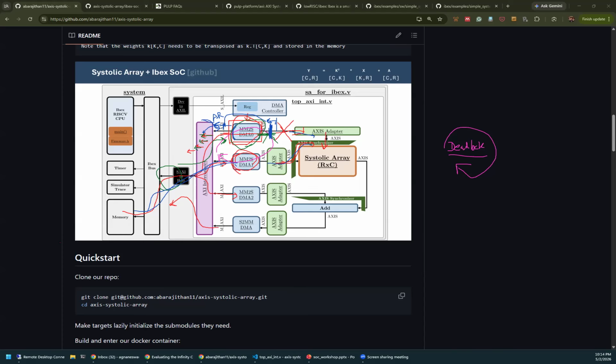All right, there is a question. When I went through the open source AXI repo, I found the AXI interconnect cannot have concurrent read-write transactions. Is that the reason you use the AXI crossbar instead of the AXI interconnect? Okay, so the AXI interconnect cannot have concurrent read-write transactions. So that is one of the reasons. Usually, I think the interconnect is less performant than a crossbar. So that is one of the reasons.